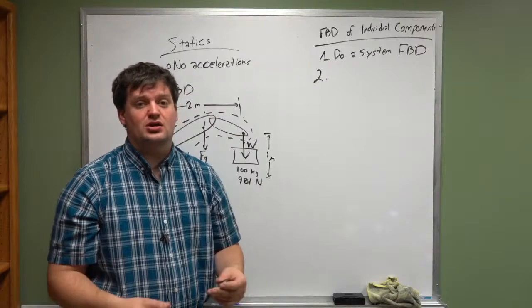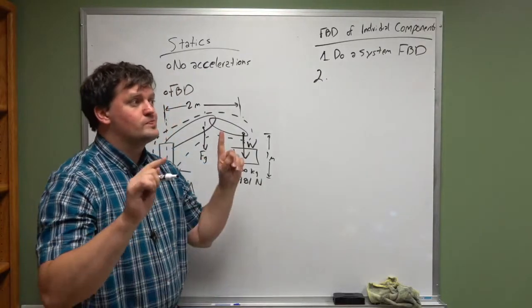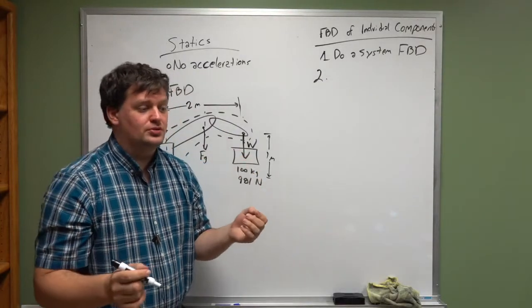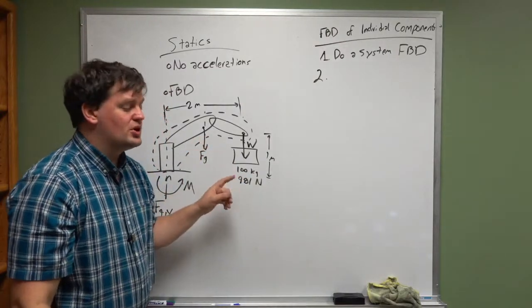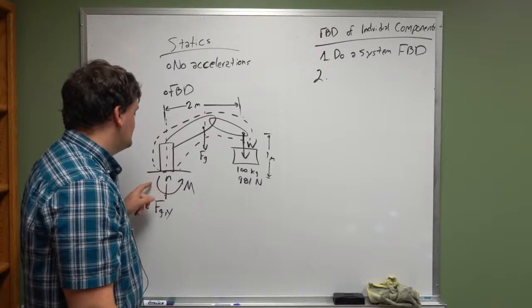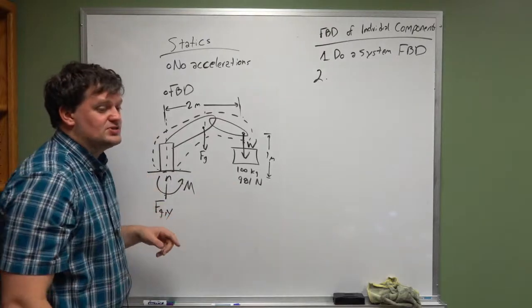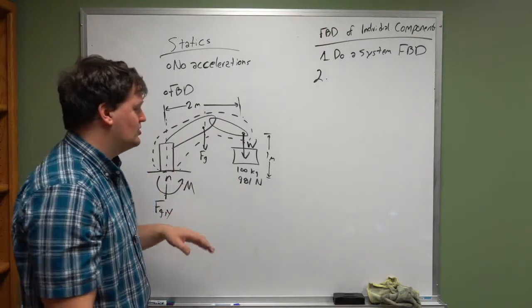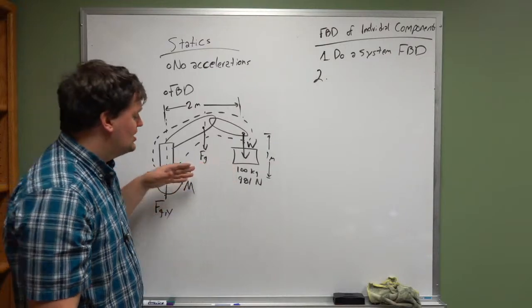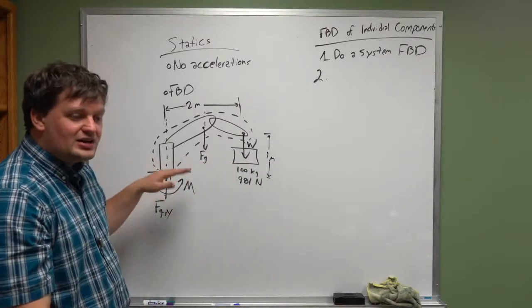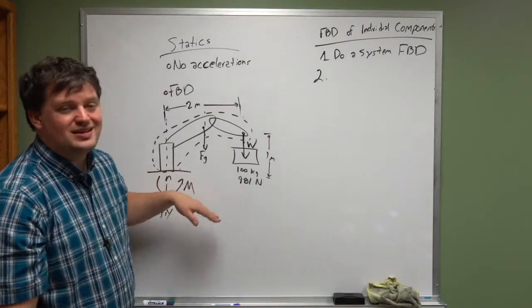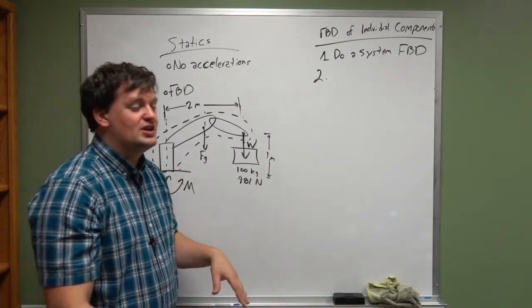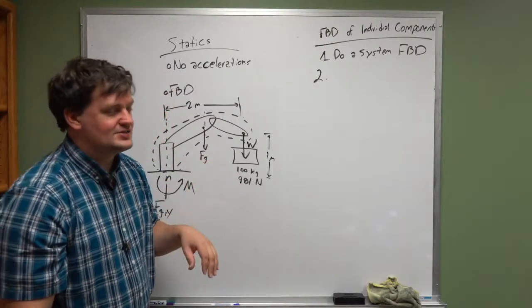It is extraordinarily overwhelming. So, the best thing you can do is start with the first component that is loaded with some outside force. Okay, look at where an applied force is. Or if you figured out what the force and the moment is here, go to there. And this is a boundary force. Pick either an applied or a boundary force and the component that it directly acts on.